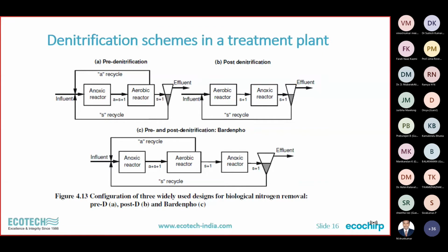Here in this anoxic reactor, we now maintain a low dissolved oxygen regime, so that the denitrifying bacteria use the oxygen from the nitrate recycled back here and liberate nitrogen gas. And for food, they have enough BOD coming in from the raw sewage. So it's a very simple process. Once you set the recycle rate, it runs by itself, automatic.